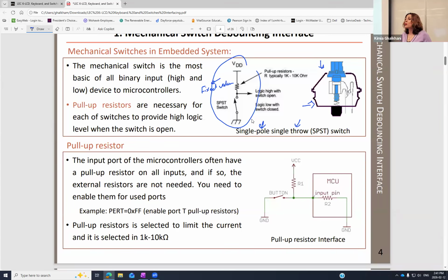If you can recall from the big schematic of the setup in the lab, which I continuously show you during the lab time, I already showed you on the side where you have those switches. On the left side of those switches, you have this pull-up resistor. In the previous lab, I asked you to also activate them.